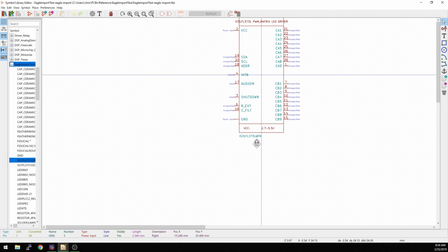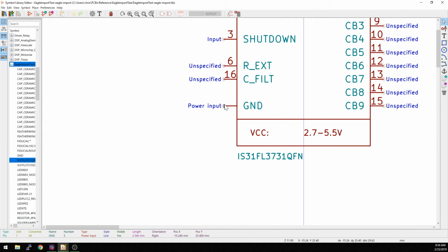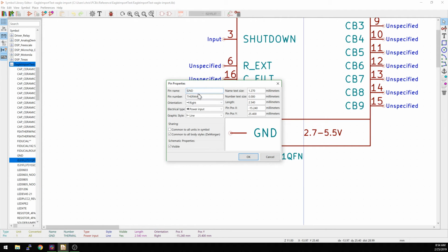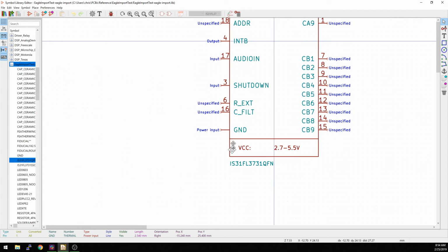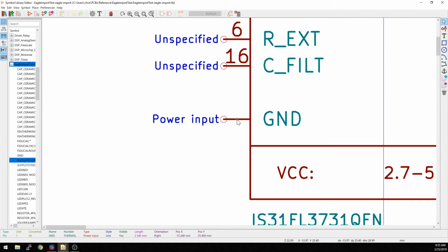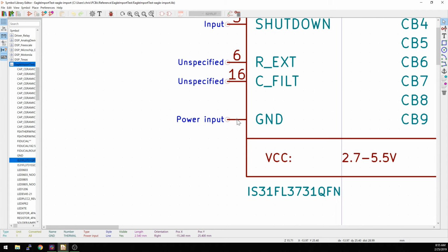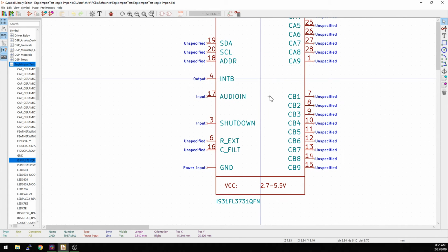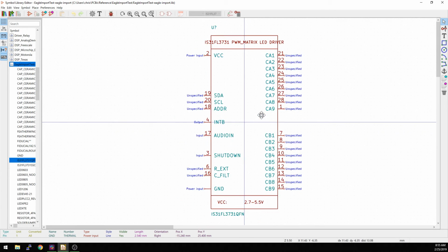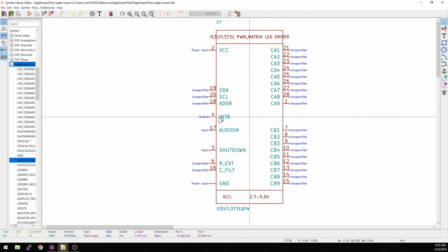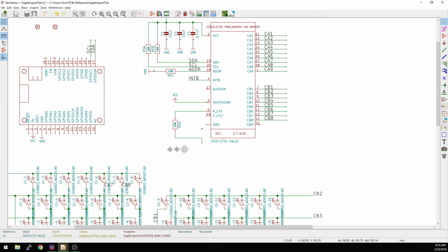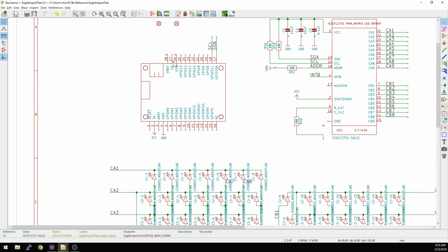But sometimes there's other things, like there's pins that are stacked on top of one another. See, there's a pin thermal, that's another one here. So in this part type, there's a center pad here, and it's connecting to both of them. It's important to note that sometimes there's pins stacked on top of one another, and there are some differences between how Eagle does things and how KiCad does things, and you need to be careful with that. So that's just one example here. Let's see if there's anything else in this schematic that we can look at.